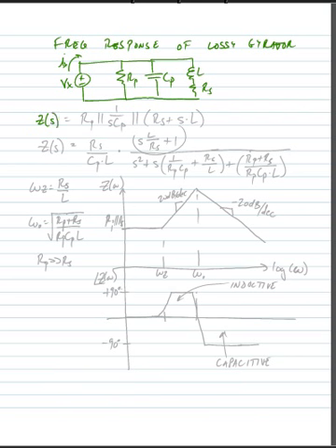that the Z of this circuit is equal to RP in parallel with 1 over S times CP, in parallel with RS plus S times L. Solving for this circuit, we would find that the impedance was equal to RS divided by CP times L, times S times L over RS plus 1, divided by S squared plus S times (1 over RP times CP plus RS over L) plus RP plus RS divided by RP times CP times L.